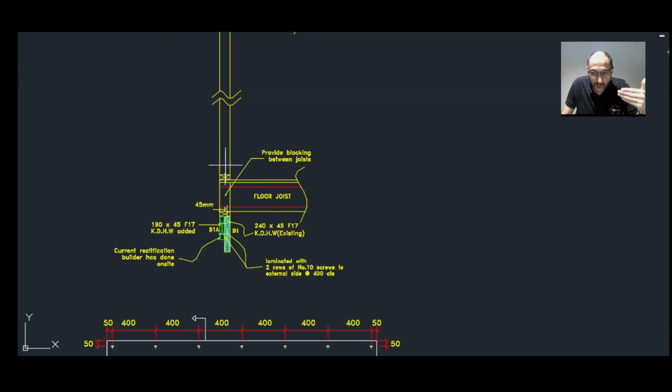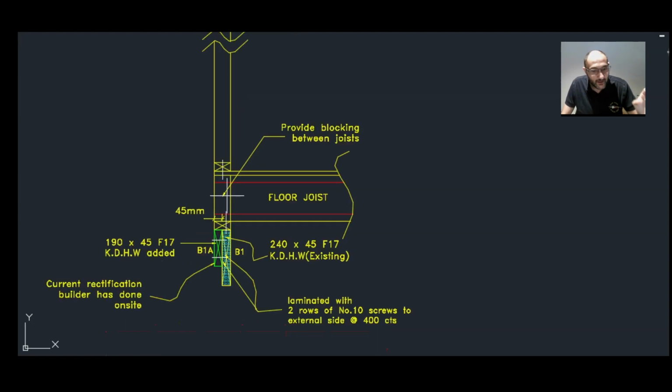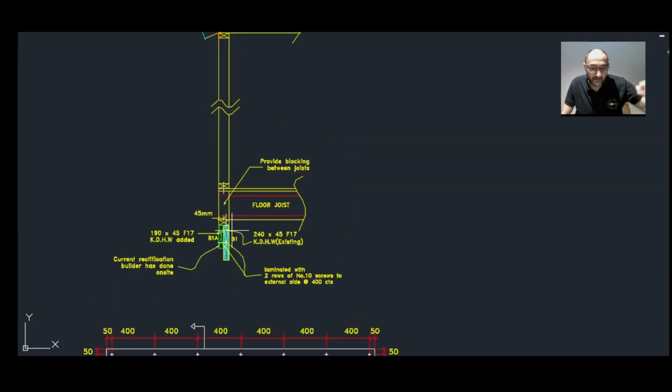So it will go through the plates, and then through the blocks as well, and then through the beam, and then right through the walls below, and finally to the slab. So you need to consider the load path of the wind pressure as well, and have you considered that in the overhang? And the third question, and that's the final one, you may want to ask is,